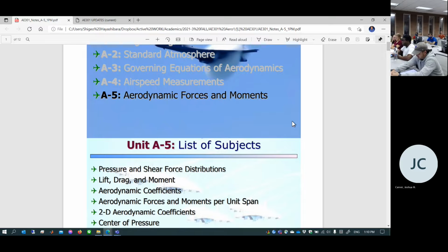Of course, you can compute lift and drag, and also pitching moment, out of the surface pressure distribution, because that is essentially the mechanism why an airplane can have lift, drag and pitching moment. Everything is driven by surface pressure distribution. So wind tunnel testing often comes with pressure distribution measurement. Now, how can you pick up that data to resolve into lift, drag and pitching moment? That's the central theme of this A5, so don't miss it. And quiz 7 is going to basically conclude that.